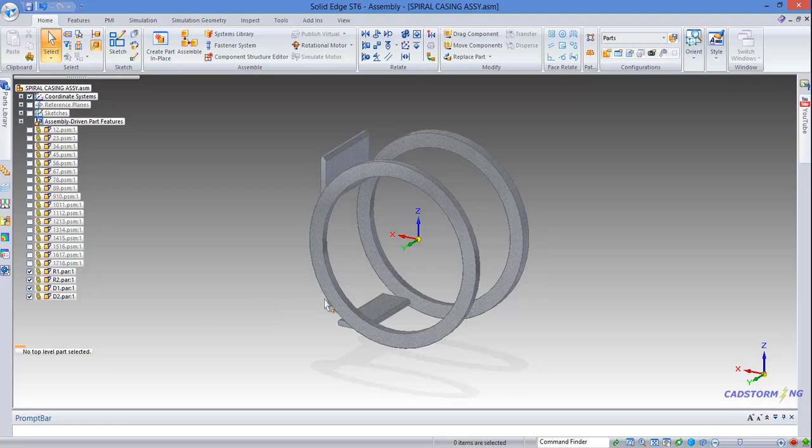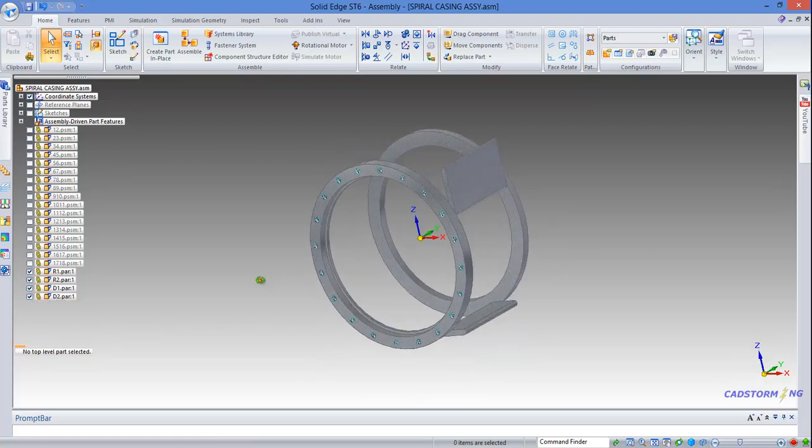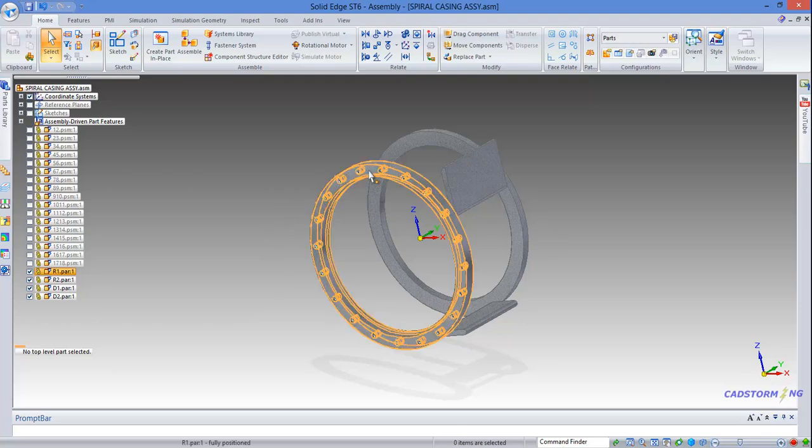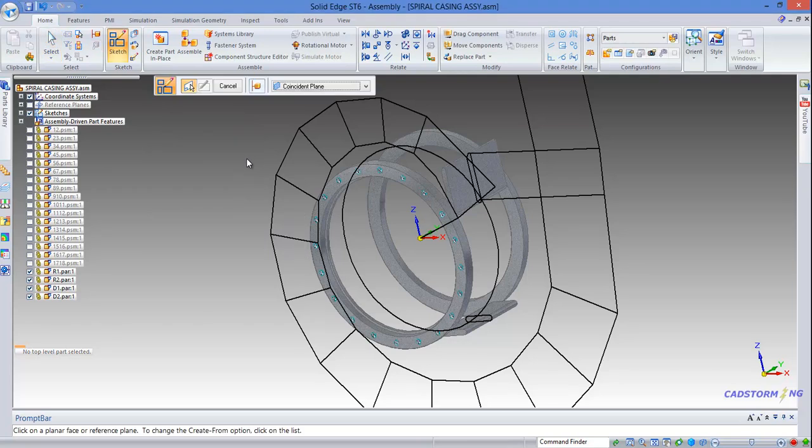Now we will use the circular pattern tool to create 2 additional instances of this deflector. As we did when we created the circular pattern of holes in this part, we need to first create the sketch that will define the circular pattern. We will make sure sketches are visible. Then we will start a new sketch on a coincident plane, which will be XZ.